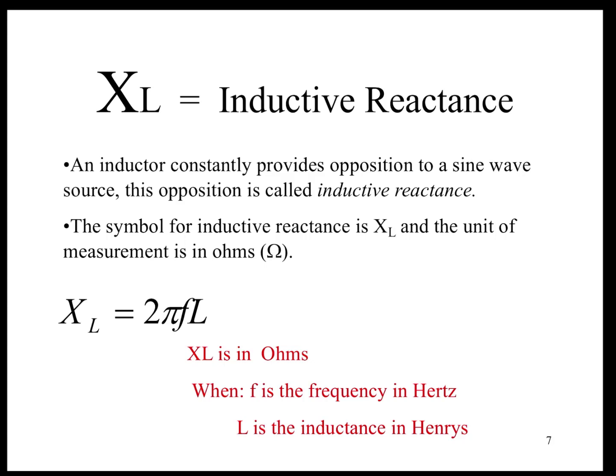And for imaginary numbers, we can have plus or minus j. And when it comes to XL, it will be plus j value. So that is to say, if you're asked to give a rectangular value for impedance for any circuit that is primarily inductive, you would always indicate the imaginary value as plus j.